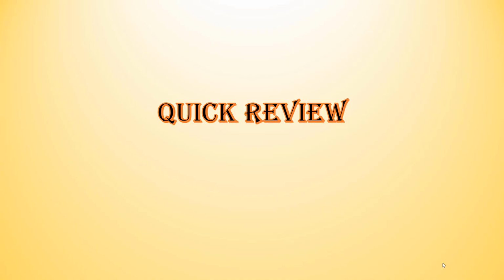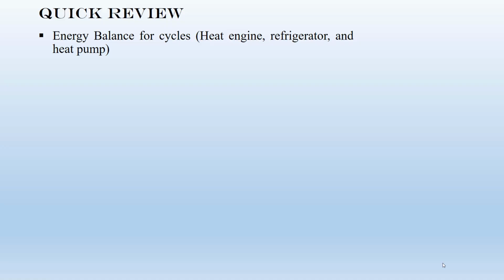So before we go over the Carnot cycle, let's just go over the previous lectures. If you remember, for all cycles, we can prove that the first thermodynamic law is Q net equals W net. If you start from the first thermodynamic law, you can simply prove this equation. So for all cycles, you can write Q net equals W net. Then we discussed the heat engines. If you remember, guys, heat engines are devices that convert Q to W.